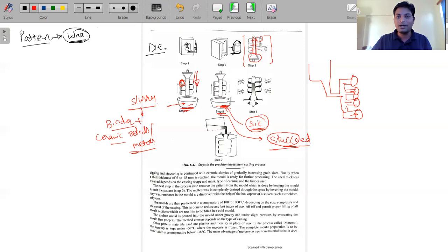So we are dipping it inside, and over that pattern, from the top view, first we keep it inside, and then we fill these refractory materials over that. The binders are already there, so it is still in liquid form. When you fill the silica sand over that, it will attach over the surface of this coating, so that it will make a smooth coating.